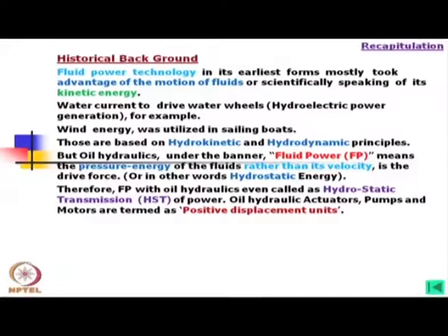the output end. In the case of hydrostatic machines, which are also called positive displacement units, instead of adding kinetic energy, the fluid is trapped in a volume. Then this is pushed out at the other end to give the pressure and also the velocity. So, in other words, the pump in hydrostatic units does not pump the pressure, it pumps the fluid, and pressure is experienced by the load.